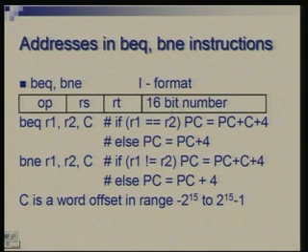So, the address which is being provided here is actually an offset, again positive or negative, with respect to the current position in the program. So, in a program if you are jumping 4 instructions ahead, then you will give a positive offset corresponding to that. If you are jumping back like in a loop we had, you will have a negative offset.